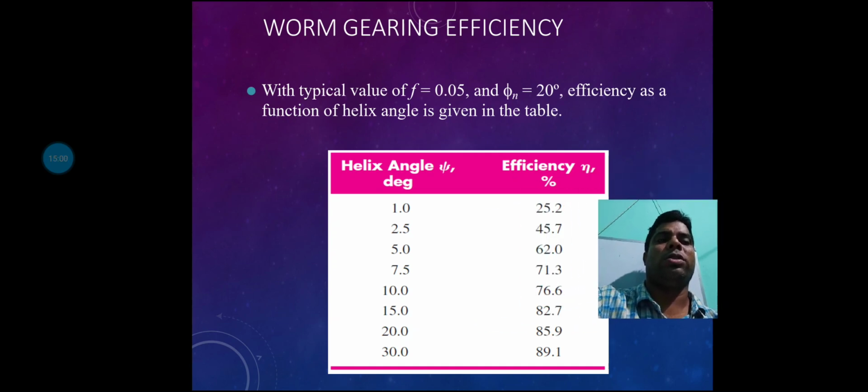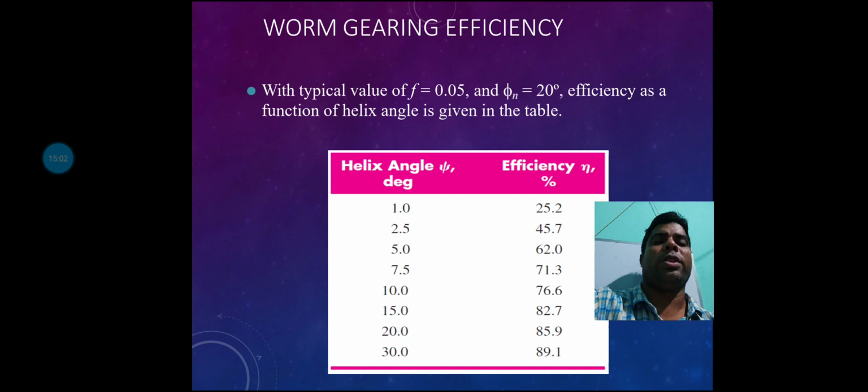And that is the equation which relates the helix angle to the efficiency. If the helix angle increases, the efficiency also increases.